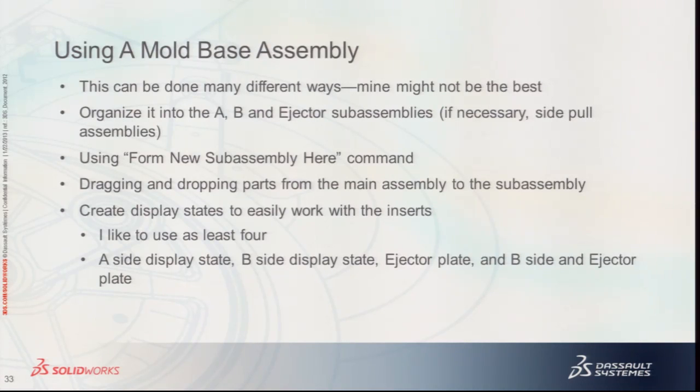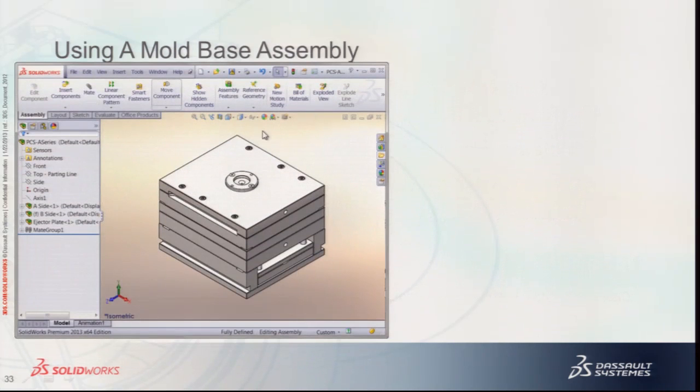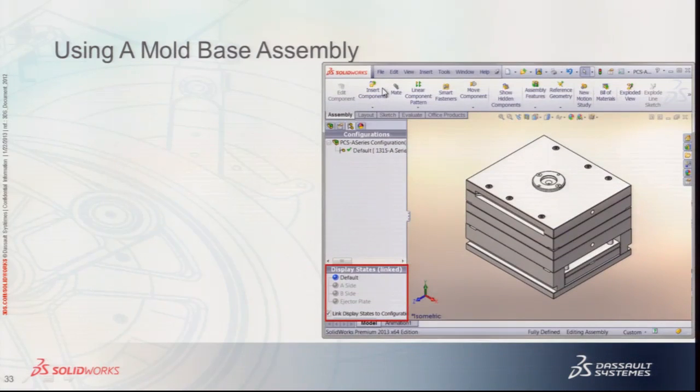I'm not saying my way is the best way, but I thought it was a good way to organize your assembly so you can use it. Basically, I make sub-assemblies, and then take it one step further and make display states to hide and show what I'm working with when I'm putting things in the assembly.